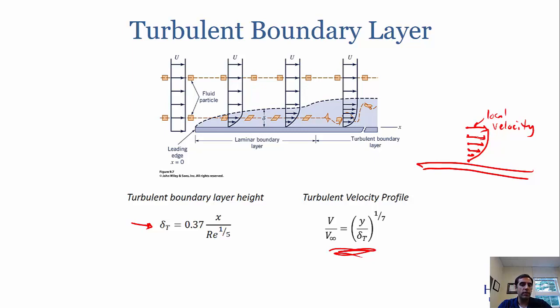Remember, the critical Reynolds number is this value of the Reynolds number below which we would expect laminar flow and above which we would expect turbulent flow. So we're going to take these probes and move them to the front of the plate, to the middle of the plate, and to the back of the plate, and we're going to change the flow speed in the tunnel to give us 6 different Reynolds numbers to determine how these velocity profiles change with Reynolds number.